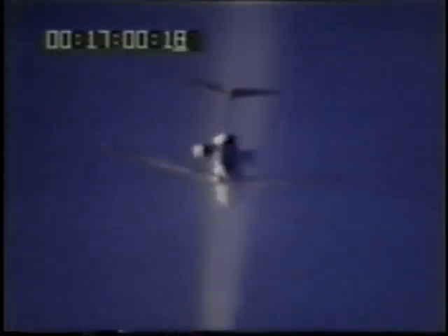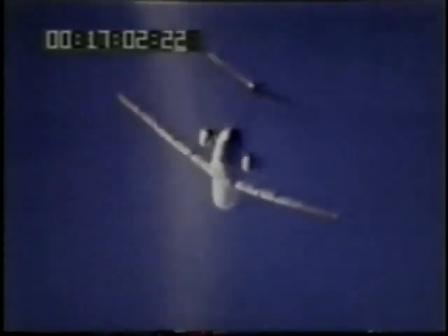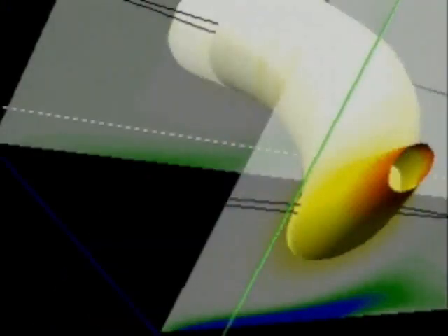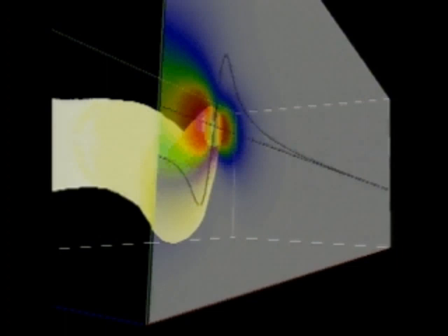The wake vortices that spiral from the wingtips of aircraft pose a potential hazard to airplanes that follow too closely. To assist in the analysis of wake vortex data, ICASE researchers have developed a tracing algorithm to extract vortex cores from simulation results, a surface tiling algorithm for visualizing the boundaries of the extracted vortices, and a feature enhancement algorithm which facilitates volume rendering of the interior of the vortices.